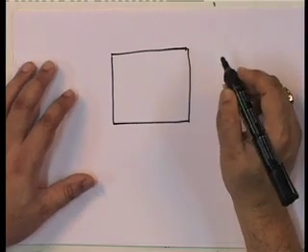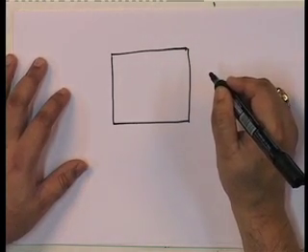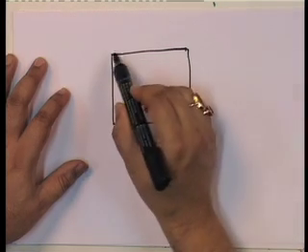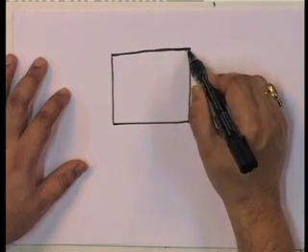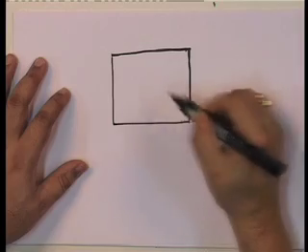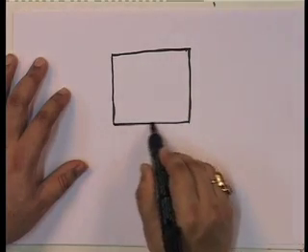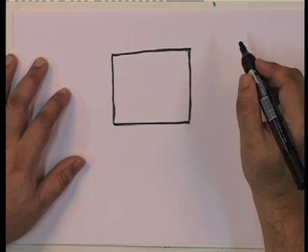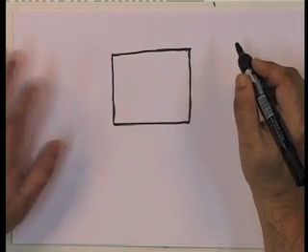Typically in such a situation, we take advantage of the fact that in buildings the slab at every floor is considered to be rigid in plane, and a slab is completely flexible out of plane.